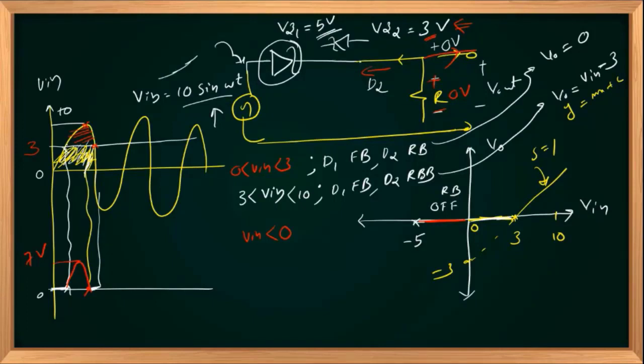So this diode was connected like this, cathode was appearing here, so this will remain in short circuit mode, or closed, or on state. Here it will be open first, so we got 0 output. Now it will break down. Once it is in breakdown mode, your cathode will be positive. You should take care about this. Cathode will be positive, anode will be negative, and breakdown voltage is nothing but 5 volts.